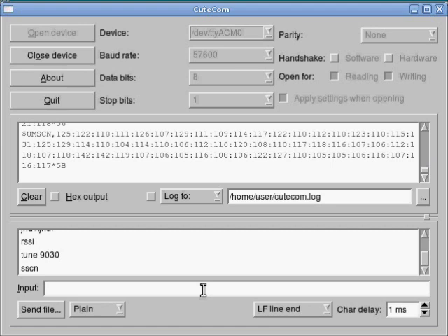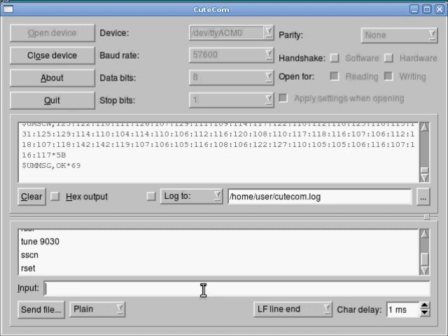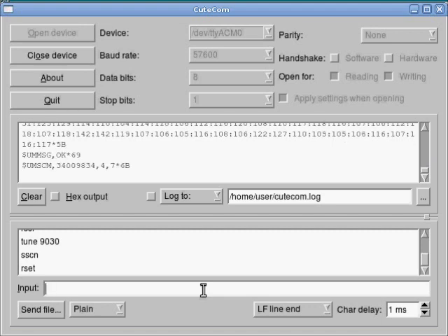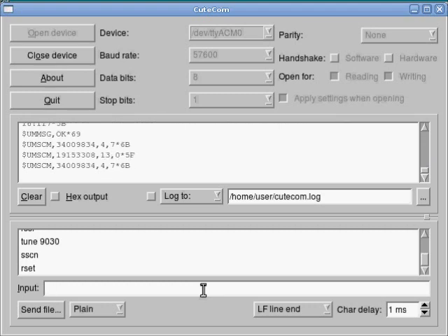So we've covered received signal strength, we've covered the spectrum scan. Let's cover some other basic commands. I can do an rset, which does a full reset on the system, and it'll take a minute for it to come back. There we go. Now it's receiving again. It flashed several times, went through its startup sequence, and now we're back to receiving data. So that's as if I had unplugged it and plugged it back in.